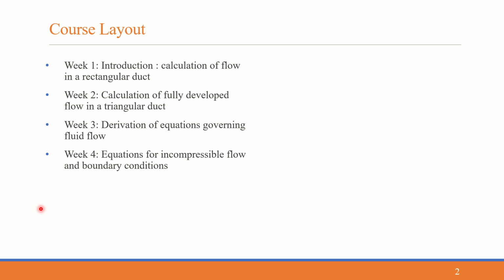And there are various types of boundary conditions like Dirichlet boundary condition and Neumann boundary condition. In Dirichlet boundary condition, what we do is that we give a value to the variable. For example, in our case of water flow in a pipe, we are giving the value of the velocity. So that is Dirichlet boundary condition. On the other hand, we have Neumann boundary condition. Neumann boundary condition is nothing but here we are specifying the value of the derivative of the variable.